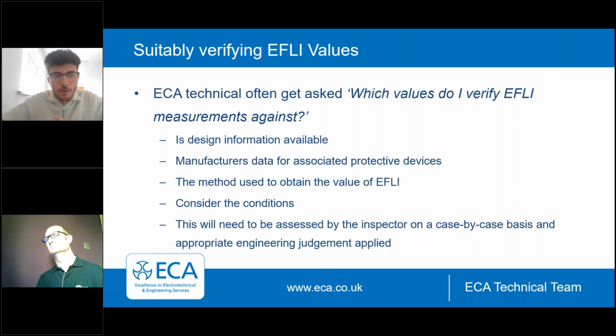It's not a requirement to confirm against design data, but it's going to give you a good indication. If your value is considerably higher, you know, quite a bit higher, then it may signify that there may be something not quite right there. So there's that to consider. We then have manufacturer's data. Appendix 3 of BS 7671 encourages the use of manufacturer specific data. This will be less onerous than the values within BS 7671, so this is encouraged.